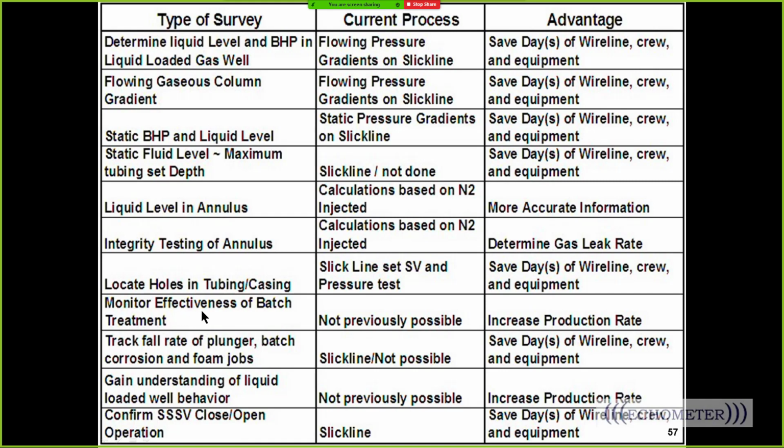a fluid level shot. We tracked plungers for a while at the beginning before we realized a plunger makes noise and you can hear it, but you can shoot levels and track a plunger or a batch treatment. The main thing you can gain is knowledge about how gas wells work by shooting levels. That's been a big benefit, understanding how gas wells work by looking at the data we collect on gas wells. And also you can check to see if standing valves open or close.